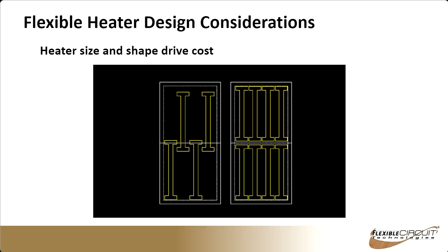That's why I said if you have a very large circuit, in this particular case, if these were cut in half and you had 2 parallel heaters that covered the same area, it would probably be considerably less expensive than ordering just 1 large one. So that's something to keep in mind. And we can help steer you to that also. If we find an application where there's something that's a big cost driver, we'll typically try and flag that and give you some steering on how to design it better.